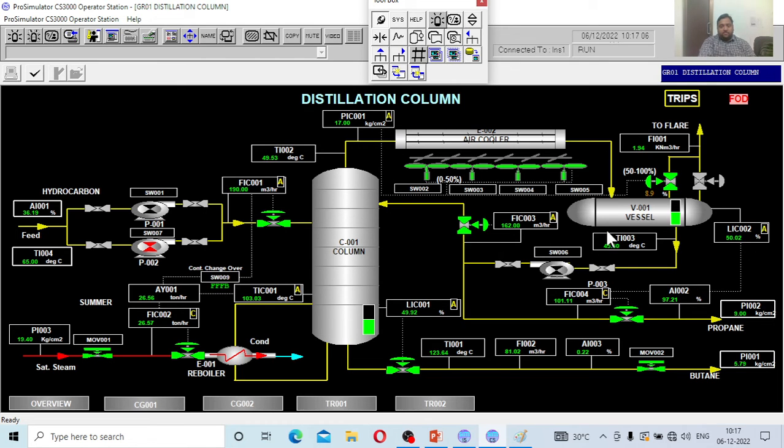If you wanted, you can play with the simulation environment in a much better way. Imagine, as you have studied in the class, if you increase the reflux into the column, the purity, 97.21, whether it increases or decreases, you are going to understand.